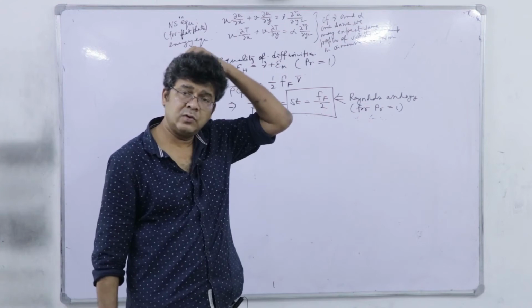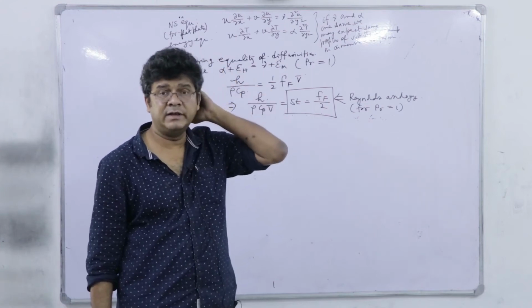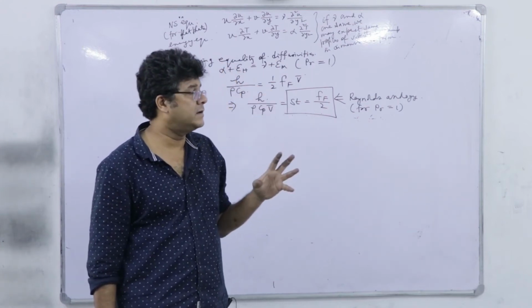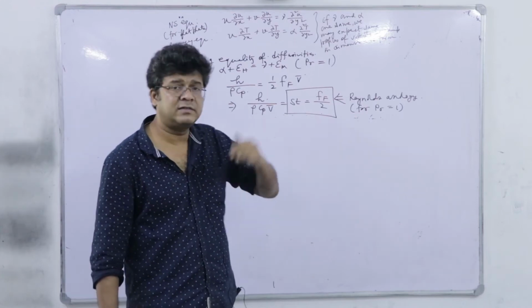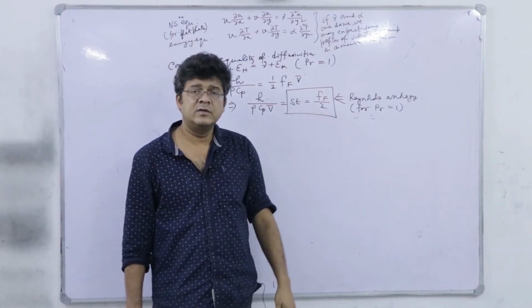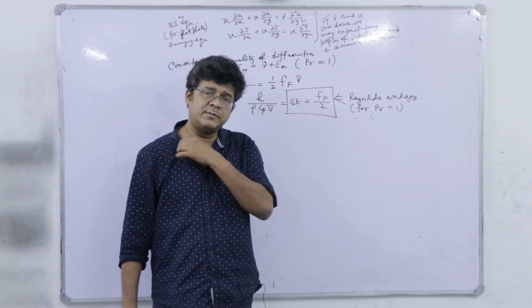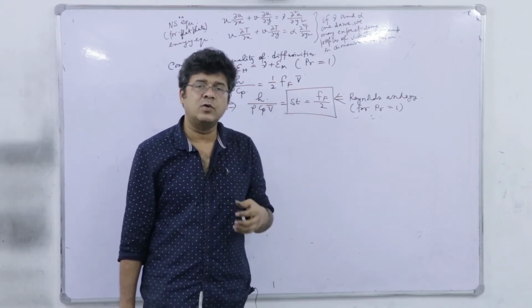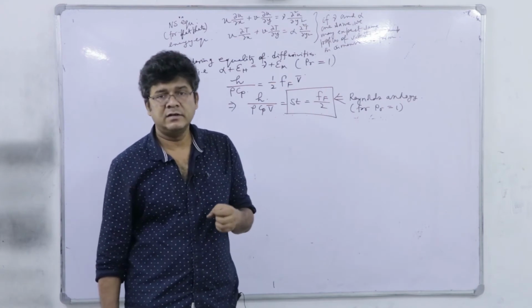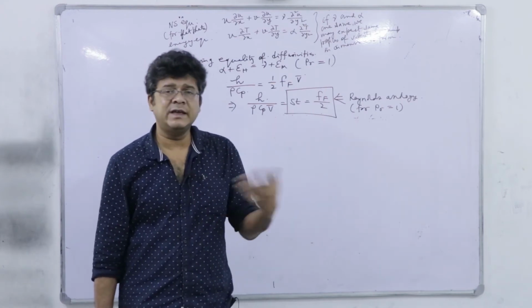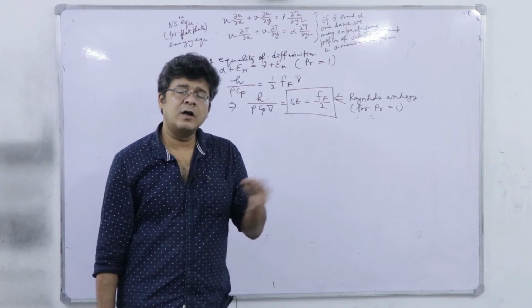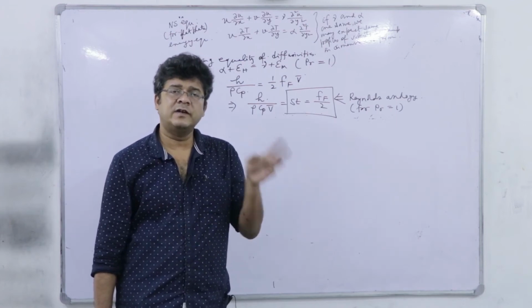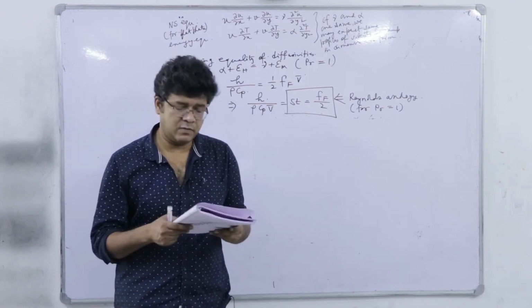What is important to note here is that in the Reynolds analogy, the 3 different layers that exist in fully developed turbulent flow in a pipe, that is the laminar sublayer, buffer layer and turbulent core, were not considered. That was mitigated simply by augmenting the diffusion coefficient by the respective eddy diffusion coefficient.